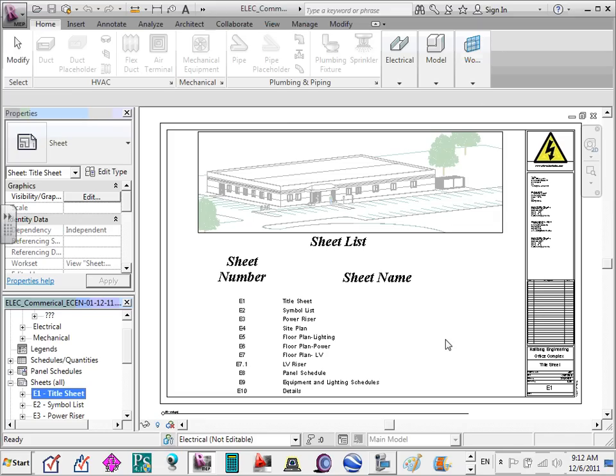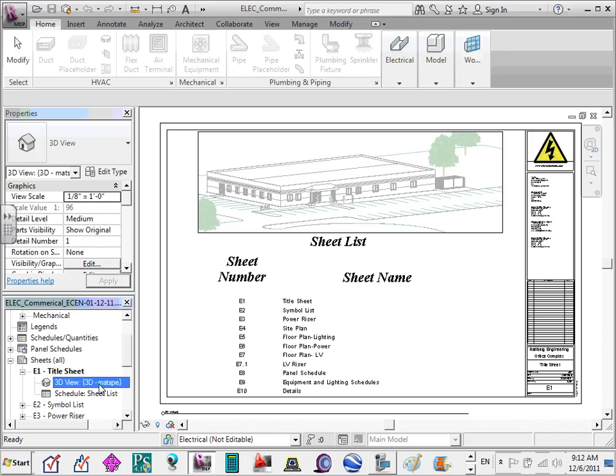This is how your title block is going to look. This is where I want you guys to wake up. Unlike CAD, all these things inside the drawing are actually links. Look at the picture, how nice it looks. If you expand it, inside it there are two files. Can you see that? That's how you bring things to the sheet. In Revit, you drag and drop views into the sheet. Very easy. It's actually easier than CAD.